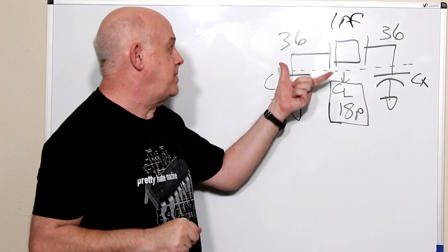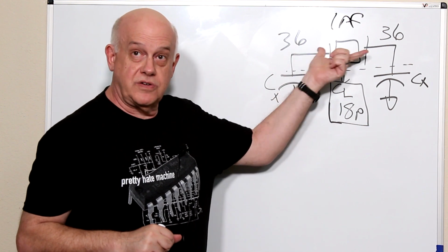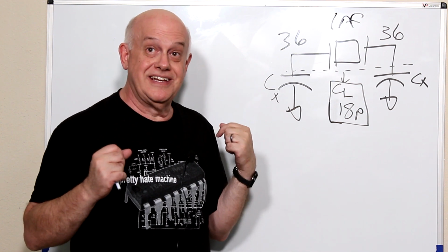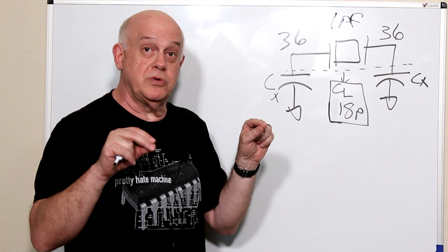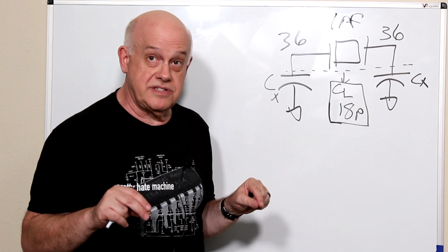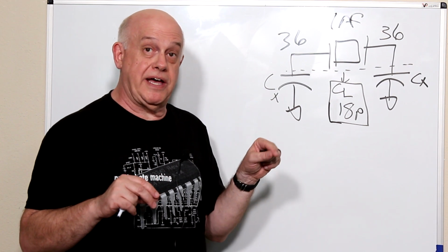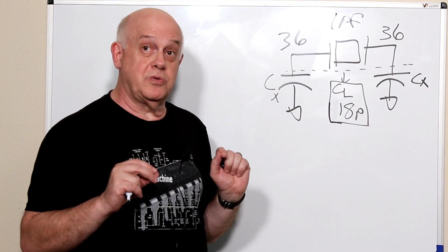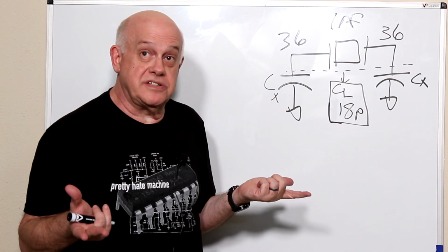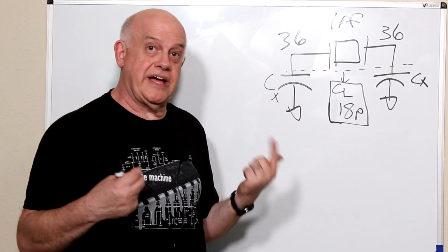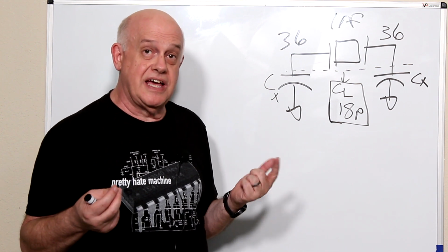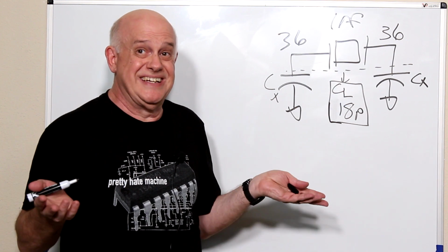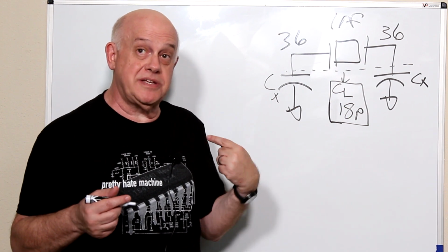But what else is this capacitor and crystal hooked to? The MCU maybe? Right. So the pins of the MCU also have a capacitance. They also are going to have a different capacitance if they're plugged into a socket. So you have to take that into account. Well, some data sheets will have the I/O pin capacitance as a typical with no min or no max over temperature or voltage. Sometimes they make it kind of high to me.